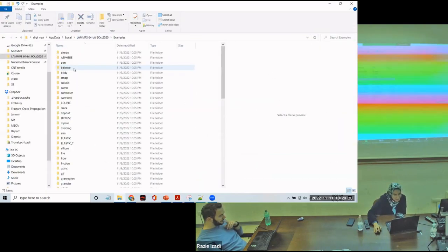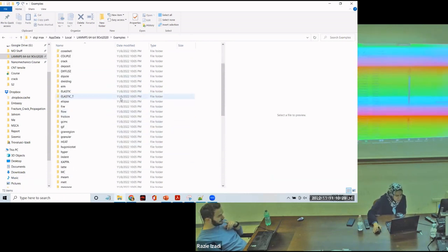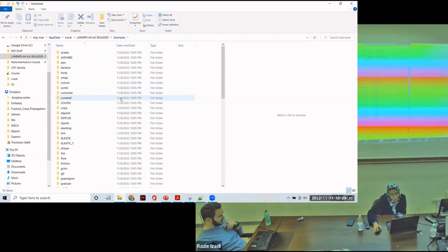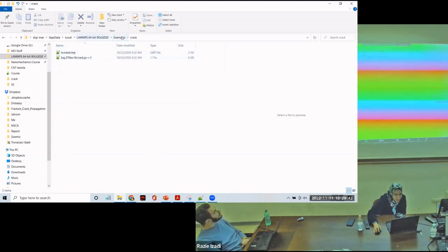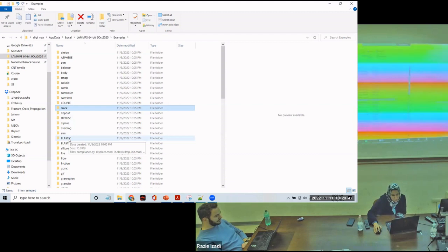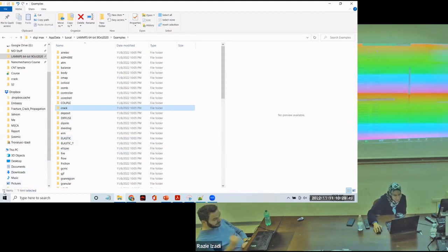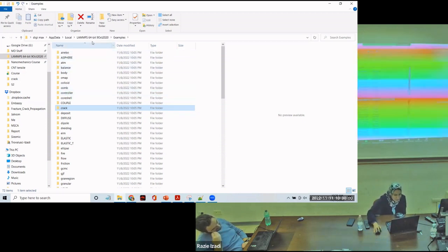And this is the examples folder. There are about 72 items, 72 examples that can be run on LAMMPS. The lowercase ones usually have just one script to run, but the uppercase ones include some other examples. So it's even more than 72 examples. And if you want to run a simulation, it's better to start from a simple script that is relevant to yours, and then improve it little by little, and then make it more complex.